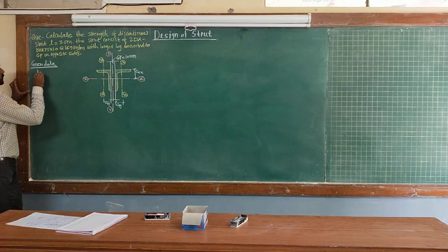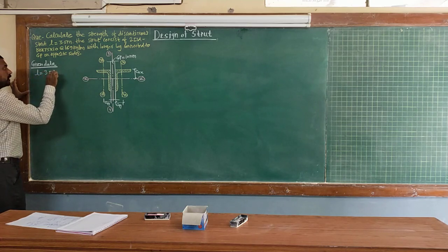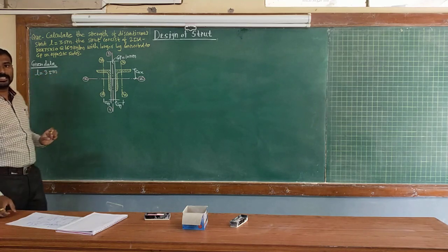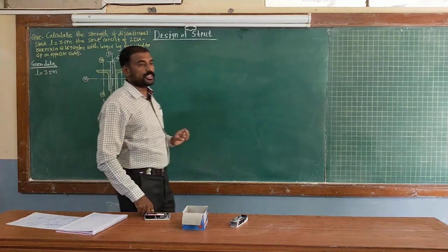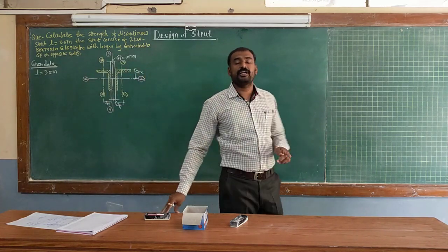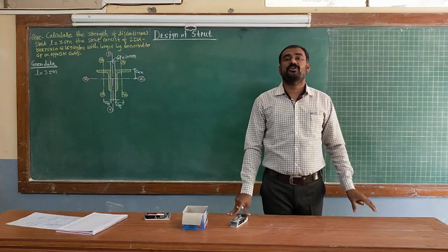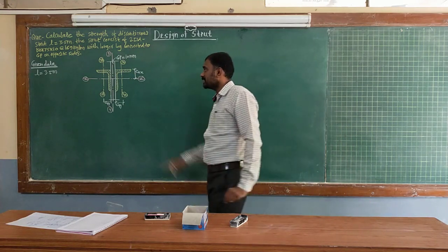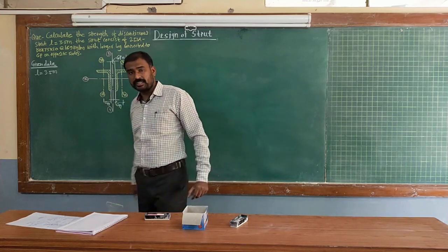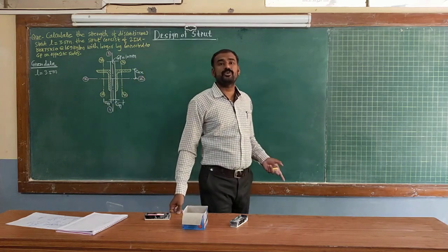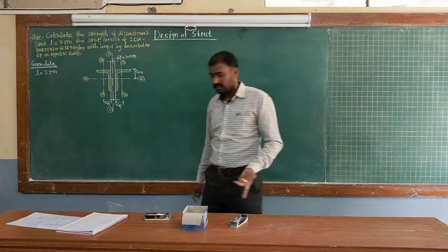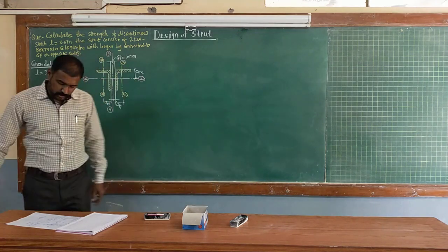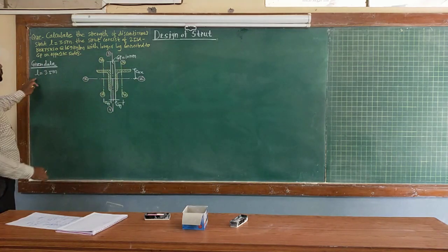So the length between the intersections is given as 3.5 meter. Here you need to understand that the effective length calculated for a discontinuous strut depends upon whether it is a double angle section or a single angle section connected. So here in the numerical they are mentioning it is a double angle section on either side of the gusset plate. Therefore here you need to add a value of 0.7 to 0.85. Correct? So suppose we will take the value as 0.85. So length is equal to 3.5.